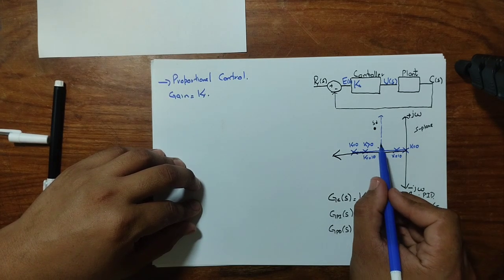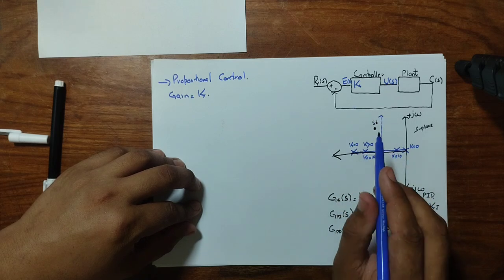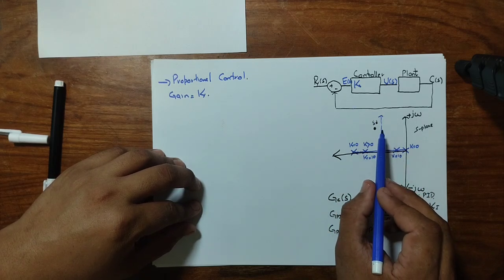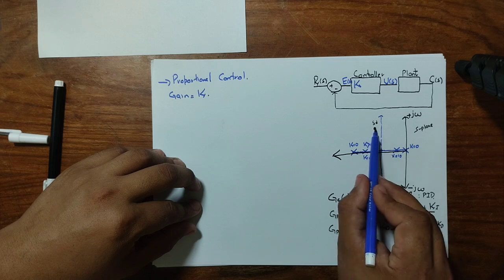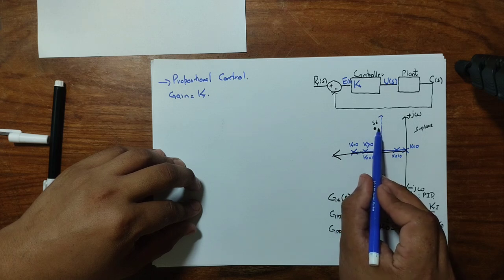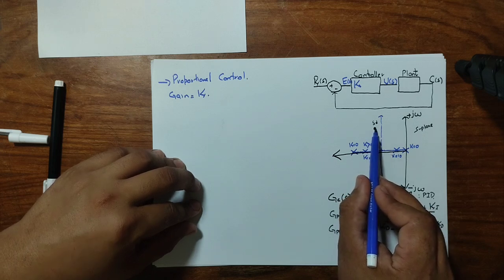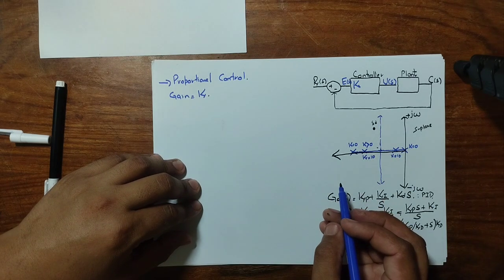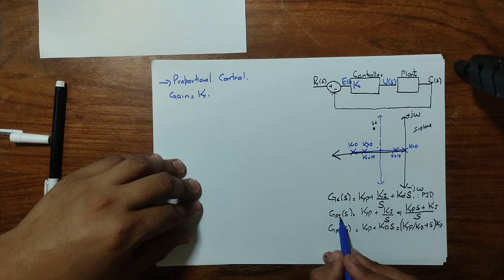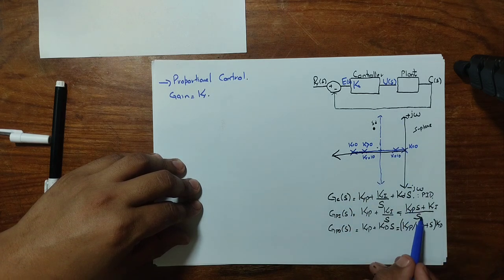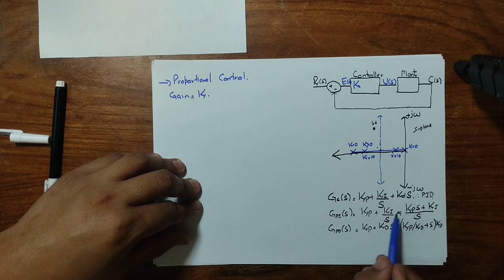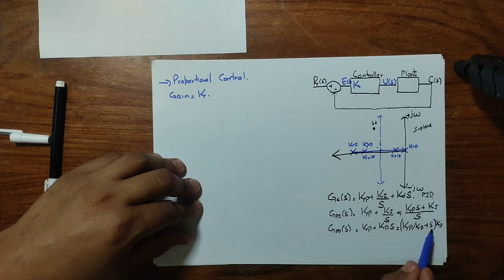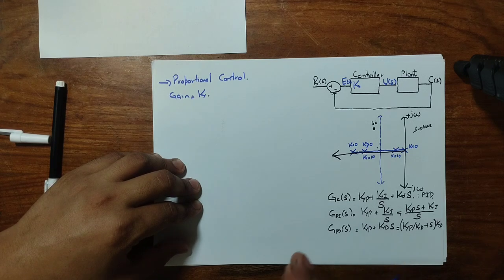So this is a typical example which shows that a simple proportional controller may not work for you in this scenario, because our desired point is a bit shifted compared to the root locus, and is at a different location. So we have to change the root locus, and in this case, we can accommodate our PI or PD controller so that we can introduce a new pole and a new zero. For a PI controller, we can expect a new pole and a new zero, right? Similarly, for the PD controller, a new zero is incorporated to achieve the desired response.